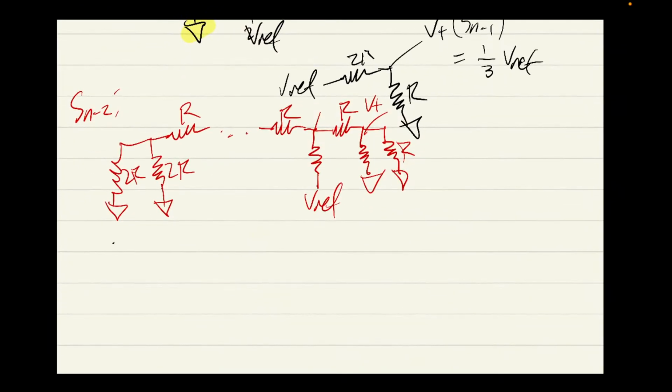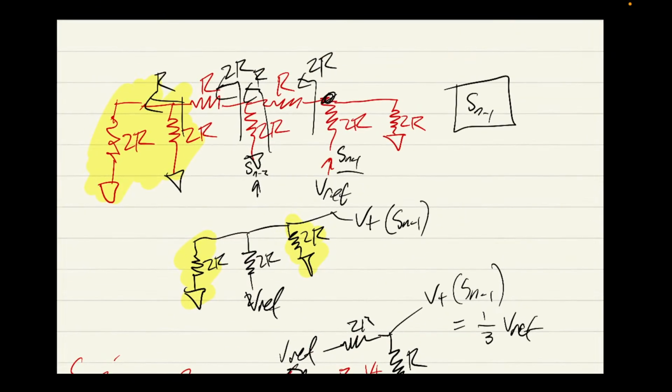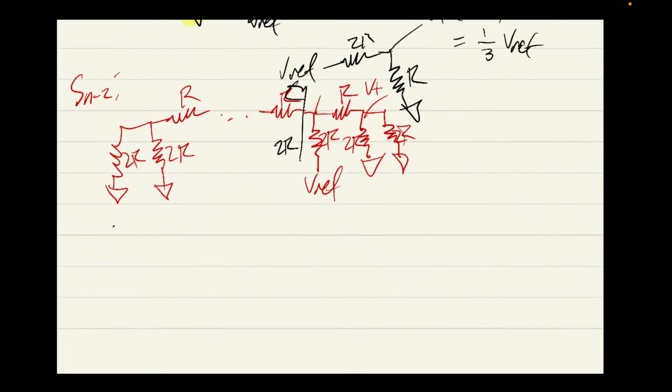So 2R, 2R, 2R, and we should be good. Now, understanding from previously, we know that looking left from over here, we end up with 2R on that side. Same working out as we saw previously. If we cut it just before the node, we get 2R. If we cut it just after the node, we get just R as the equivalent resistance looking to the left, okay?